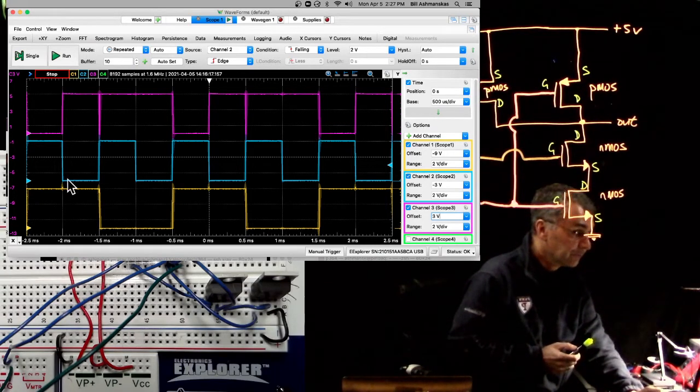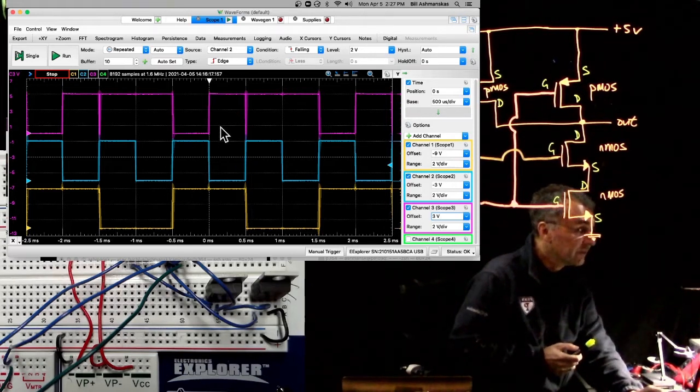And see, there's a little glitch here. That's kind of interesting. Also, I stopped the scope, so we can run it later. But you can see low, high, high, high, low, high, high, high, low, high, high, high. So it's only low if both inputs are high. And then there's a sort of interesting glitch. Let's see why that makes sense.